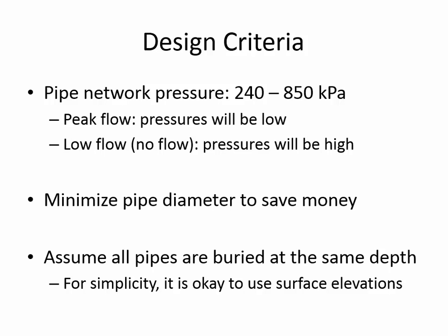Yeah, it does. It'll make it more expensive to put it higher up on the hill and further away from the town, but that's money well spent. You'll spend a little bit more to get it up on the hill in the pipe length, but then that'll allow you to make all of the sizes in the network within the town so much smaller. But you do need to consider the length between that control junction A and the location of the reservoir. And some students sometimes mistakenly confuse the spring location with the reservoir location.